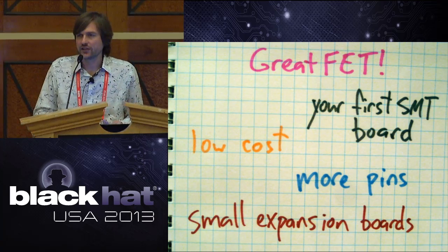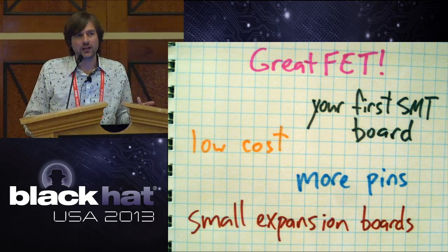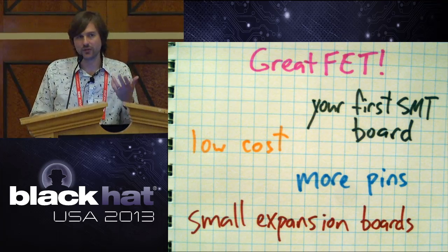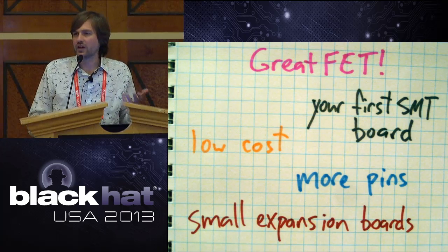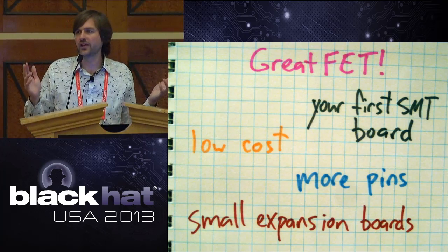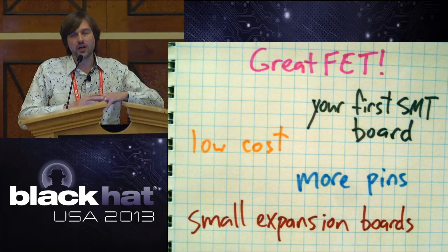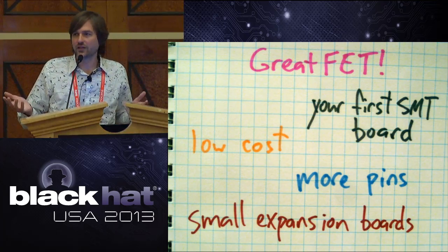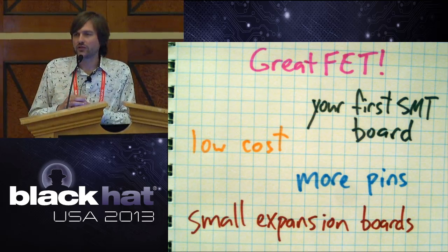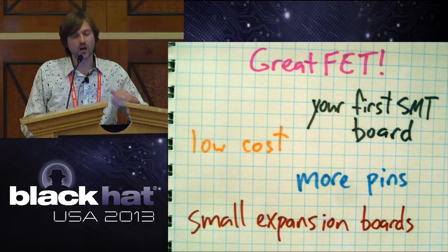It's lower cost than the existing GoodFET designs. Travis designed the GoodFET originally around microcontrollers from Texas Instruments that he was able to get free samples of. So it's a great design for people who want to build just one, because Texas Instruments will send you a free sample of that one expensive part. But anyone who's tried to manufacture GoodFETs in volume has found that that integrated circuit, that microcontroller, is really needlessly expensive. So I wanted to get a lower cost microcontroller on there.